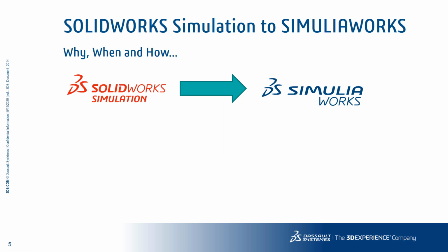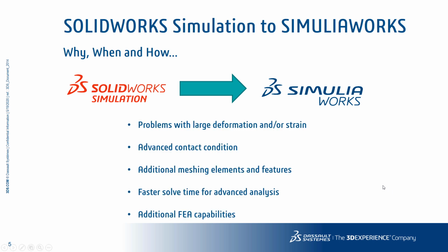So when we talk about going from SOLIDWORKS simulation to SIMULIAworks, the question is why, when, and how. A reason to migrate from SOLIDWORKS simulation to SIMULIAworks would be problems with large deformation or strain. Nonlinear problems with advanced contact conditions would be another great reason to migrate over.